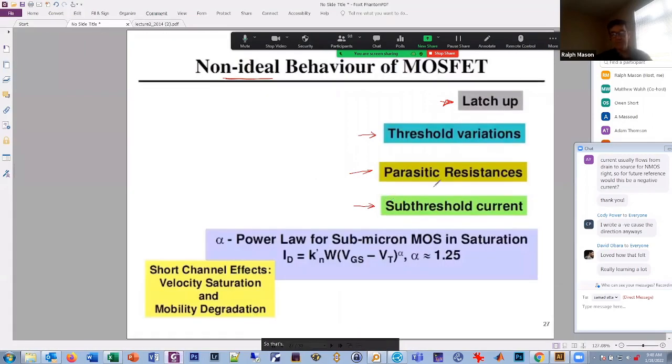So that's important. It turns out that as we shrink the devices down, we have this equation for saturation. It looks like this, and we have this. I said this is VGS minus VT squared. Well, as we get smaller devices, this isn't necessarily squared. It can get smaller, getting closer to 1. So yeah, the transistors aren't given as much current as we'd like. And we also get things like velocity saturation, mobility degradation. There's a whole bunch of things that basically make the transistors a little worse as we make them smaller and smaller. We're not going to spend a lot of time on that. I just wanted you to be aware that they exist.